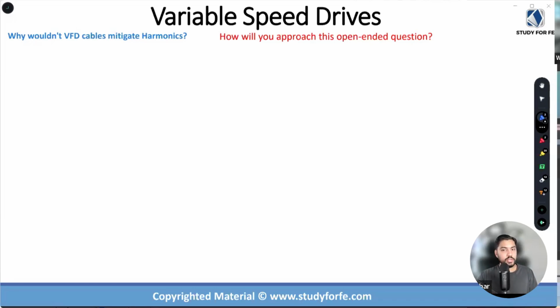Right. So we know that when we are using VFDs, the original equipment manufacturers, shorthand OEMs, always, especially for larger VFDs, they always recommend you to use VFD cables. Those of you who have worked as design engineers, who have actually worked in the field and maybe installed, commissioned, programmed VFDs, you know that VFD cables are more expensive.